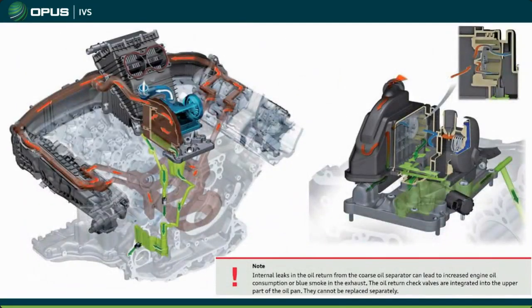So I'm just going to go through the big points of this, and how this system works. It's very similar to the rest of our systems. The red here is your blow-by gases, to be ventilated. They travel up through the block, through the head, into a hose in an integrated port or hose in the intake manifold, right? This is a hot V, so your intake is on the outside, right? It flows up through here, and into this hose and into your oil separator module. On this side of the head, it comes up through here, and it vents right onto this side.